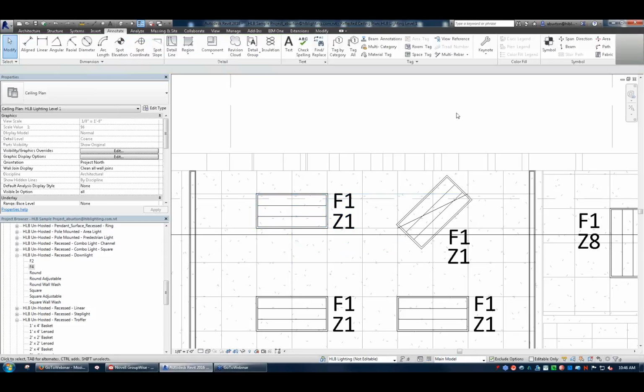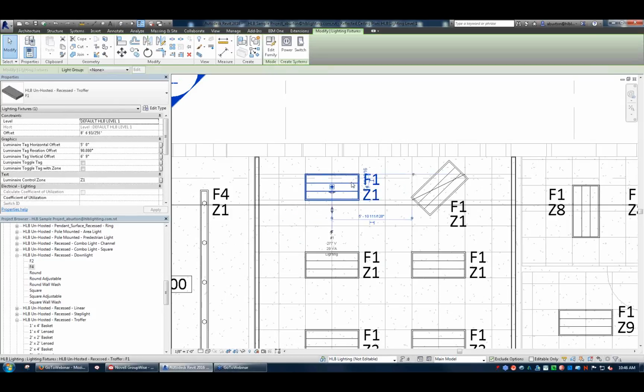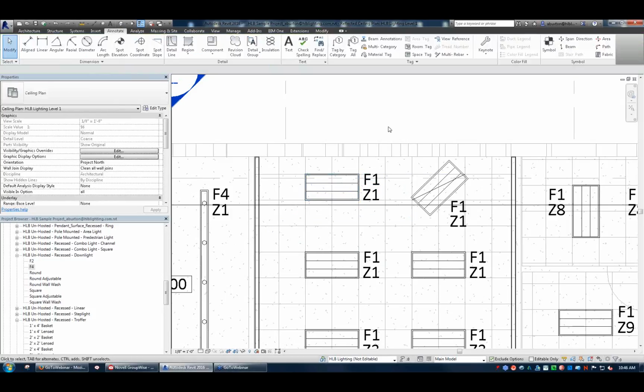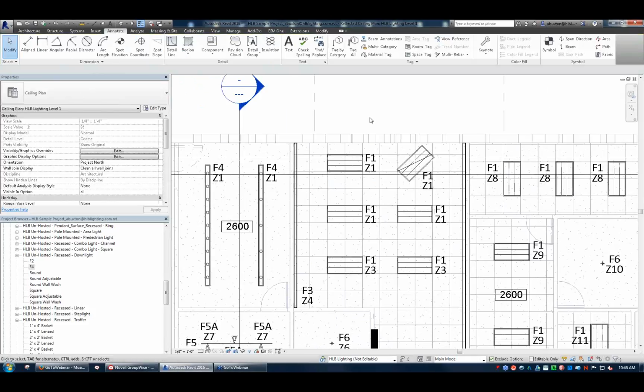Okay. San Francisco asks, should we just use the toggle keynote tagging always so they are always tagged correctly? No, I would think no. My thoughts are that unless the architect specifically wants that keynote toggle in, then you shouldn't do it, because otherwise pretty much any view that has light fixtures in it will populate with that tag, is my understanding.